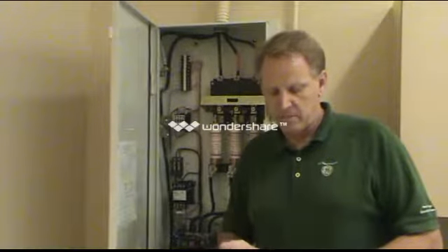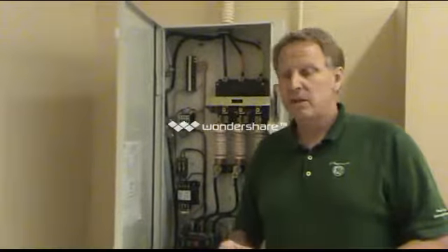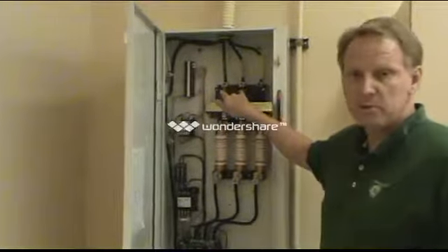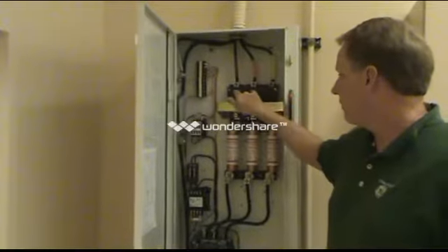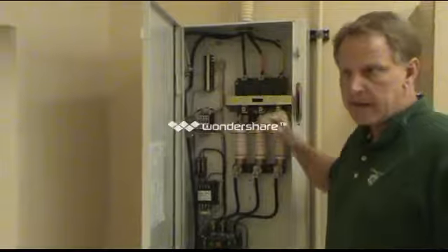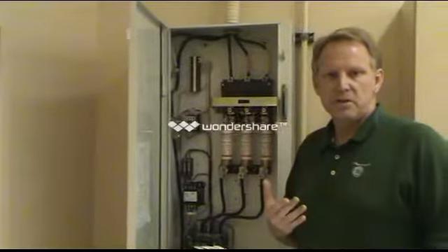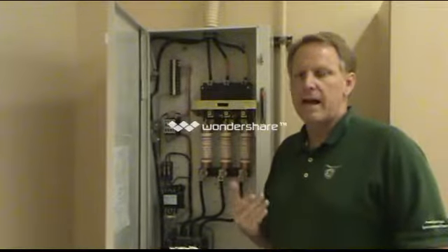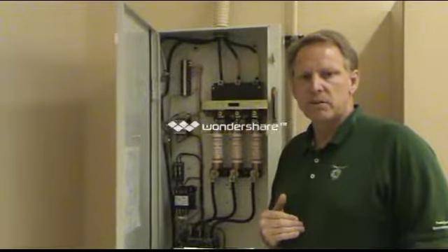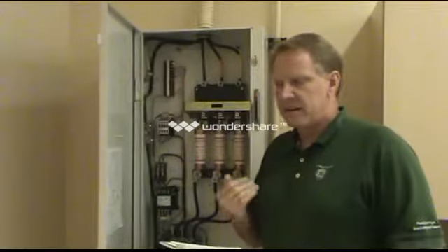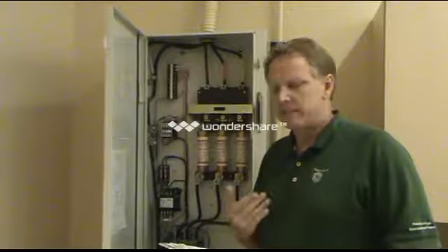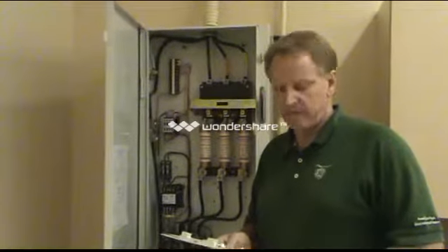All right, step 5 is the measurement of voltages. I'm not going to go through this one showing you how to do it. Everyone knows how to measure voltages. Basically, you're going to be looking at voltages between the phase to phases, all of them. They should be balanced. There should be no more than 2% difference between the low and the high. So on a 480 volt system, that's 9.6 volts. If I see a difference of more than 10 volts, then we're going to have some discussions with the facility.